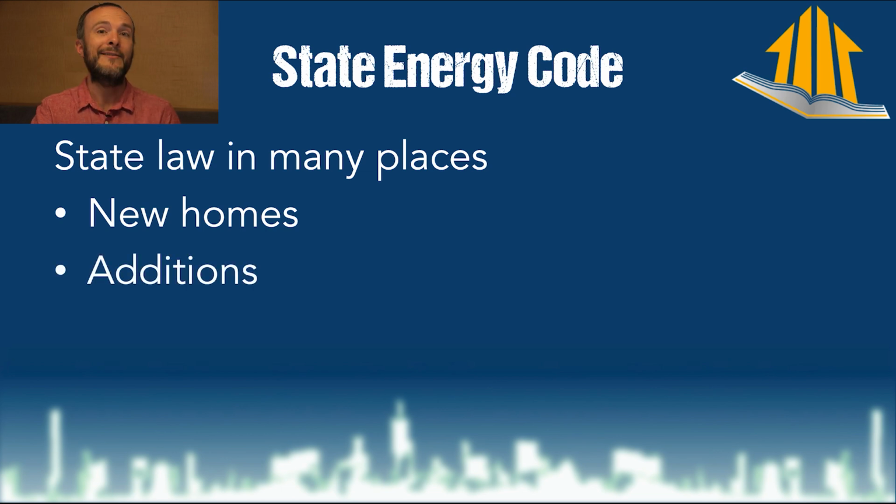You also want to make sure that if you're building an addition that you have the load calc done, because often you've got a system that was installed in the 80s and then many things happen to the house. You might have replaced the windows. You might have added more insulation to the attic. You might have then done this addition. You might have tightened up the house with an air sealing project. And now the size of the air conditioner that you had in the 80s and the size that is needed by the house, completely different. Not in the same ballpark at all. So this is also important.